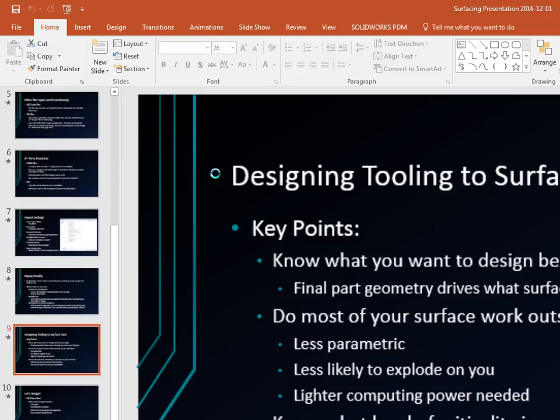This one, I think technically the draw angle was like 34.2 degrees, and I could see that on the locator features. So I just cheated it to 35 and called it good. I'm usually looking for the flat surfaces, those datum holes, and stuff like that to pick off of.